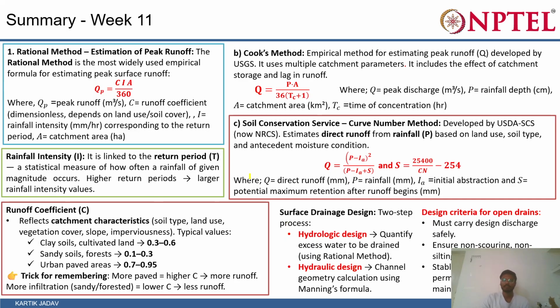We quickly looked over these aspects, and understood the limitations of the three methods and which one we need to use where. We identified that the SCS curve number method is the most accurate among the three and also the more detailed one, while the rational method is an empirical formula, more like a black box in nature.